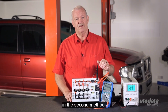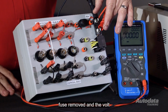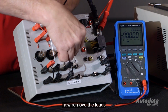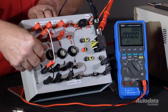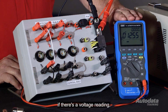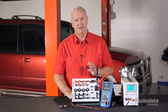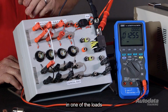In the second method, I'll use a voltmeter. I've got the fuse removed and the voltmeter is connected across the fuse holder. I'll now remove the loads. In this case, it's the light globes. I'll turn the circuit on. If there's a voltage reading, that indicates that the short is in the wiring. If there's no voltage reading, that indicates that the short is in one of the loads.